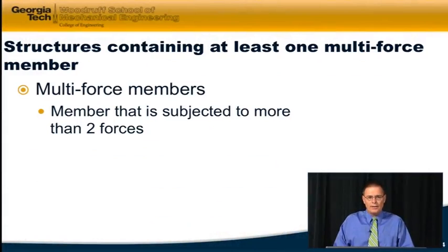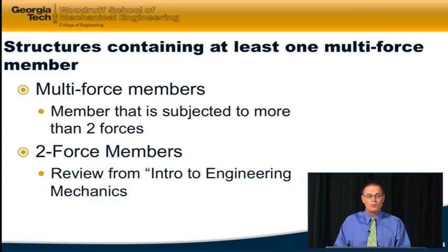So structures that contain at least one multi-force member also can contain two-force members. The multi-force members are defined as members that are subjected to more than two forces, and I'm going to show some pictures of those later on in the module. They also contain two-force members, and you should already know about two-force members because we covered that in my Introduction to Engineering Mechanics course.